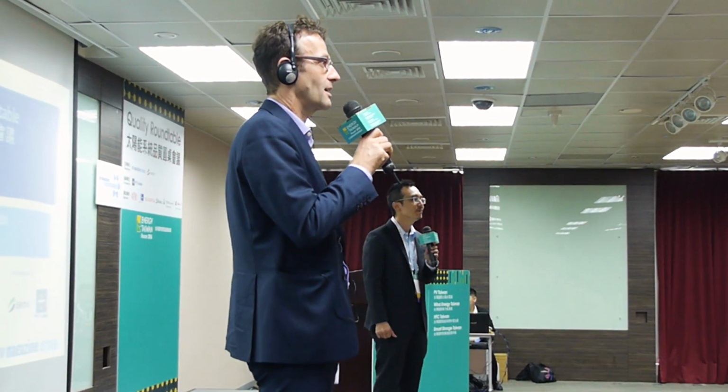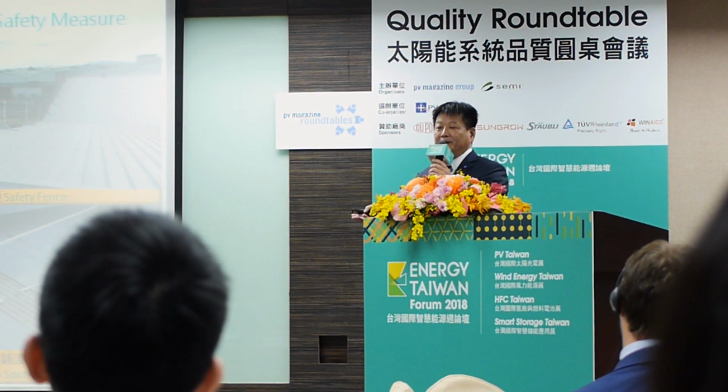Well, what was known as LID for many, many years, since 1973, was the boron oxygen defect. And the LeTID defect, which especially happens at elevated temperatures, is due to something else that's not related to the boron oxygen defect, and that is summarized as LeTID. Both effects add up to an overall degradation, and you have to reduce this overall degradation. Unfortunately, the measures to tackle these different effects partly counteract. To mitigate LeTID, wafer producers have to reduce hydrogen content in the wafers. To mitigate LID in the cell production, exactly this hydrogen is needed.